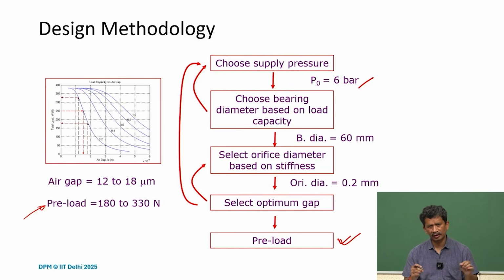So the pressure over the bearing surface area will change so that it can take the load. On the other hand, if the weight is less, the preloading is less, more air will flow and there will be a larger air gap. So it adjusts. It's self-adjusting, which is good.